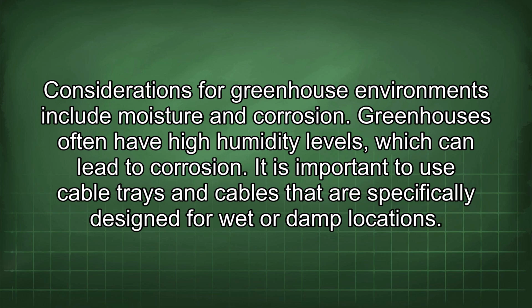Considerations for greenhouse environments include moisture and corrosion. Greenhouses often have high humidity levels, which can lead to corrosion. It is important to use cable trays and cables that are specifically designed for wet or damp locations.